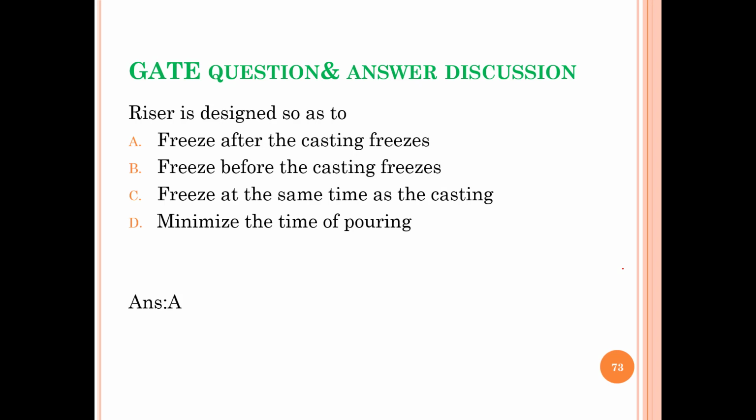Next question is: a riser is designed so as to freeze after the casting freezes, freeze before the casting freezes, freeze at the same time as the casting, or minimize the time of pouring. So we know that the riser should freeze after the casting. This is the right answer.